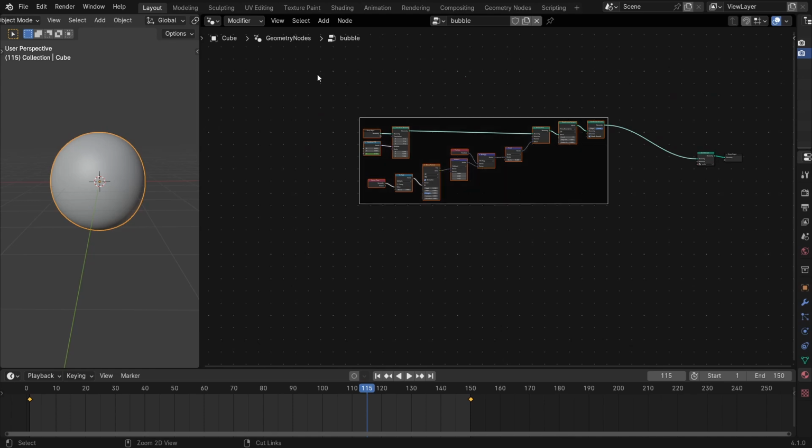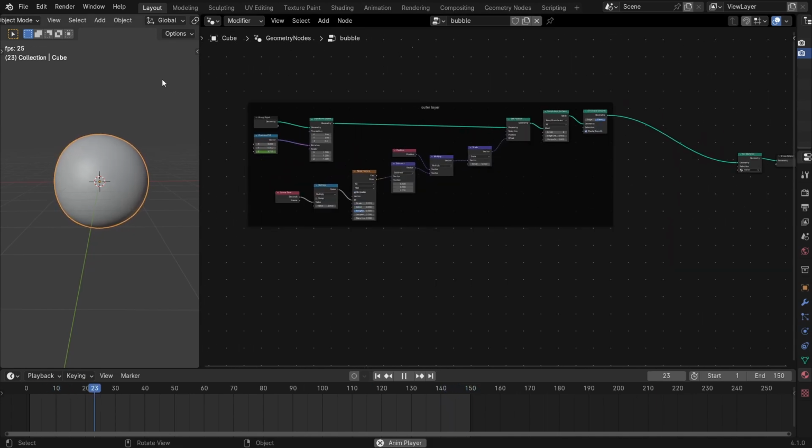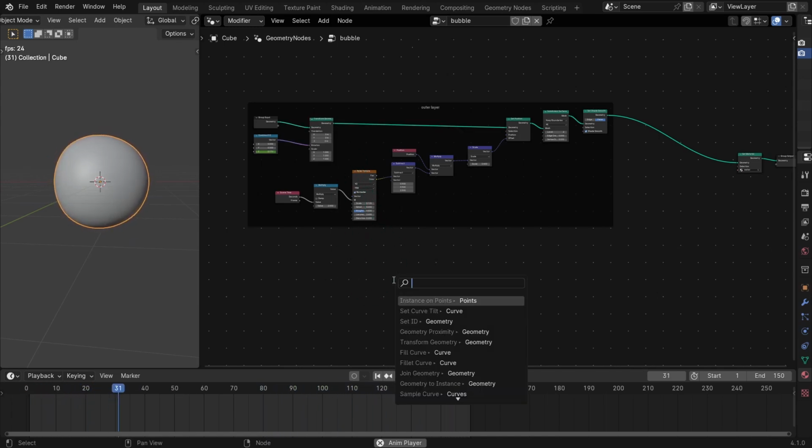So I'm going to hit Ctrl J on this. If you hit F2 here, you're going to name it to outer layer. So always keep things organized so you don't get confused in there. And you can see the zero rotation is not doing anything here. It's not much, it's not even visible. If you even mute it from here, it's not going to be visible anywhere. But now we can get this transform geometry node and use it for our instancing.